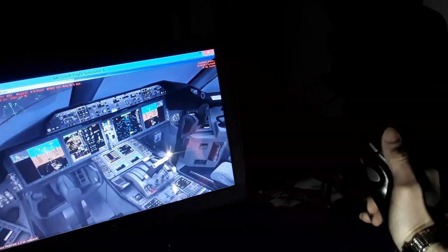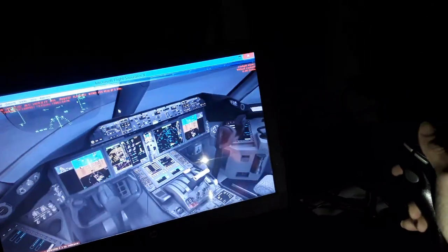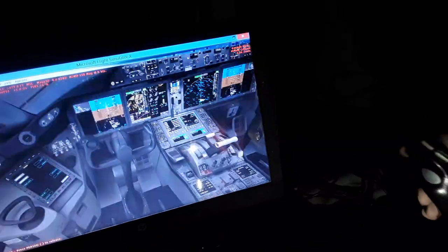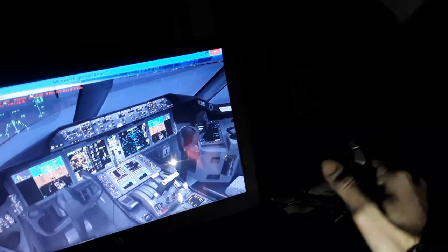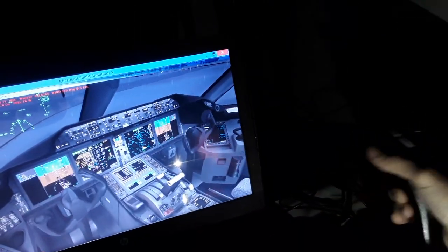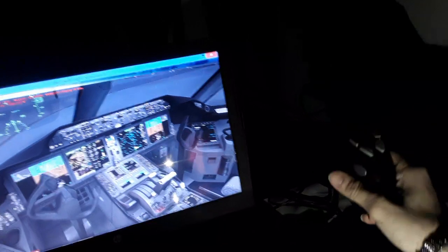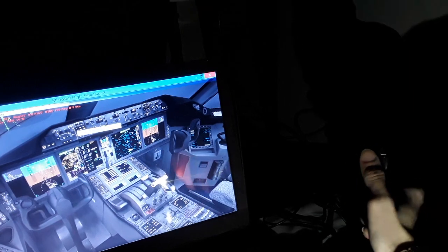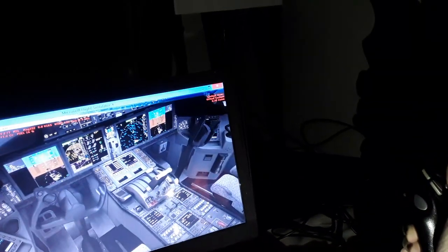So you can pick how many degrees you want to climb or descend, and using the thrust also, propulsion from the engines. The rudder pedals, as I told you, use the vertical tail, the rudder, and the side stick uses the horizontal tail for climb, descent, and turns left and right. The control wheel over here is the control wheel section. You use this to make turns using the ailerons, spoilers and the flaperons. So you can use either one or the rudder pedals, or use them all together. You will see what happens with the rudder pedals, for instance, or the yoke.